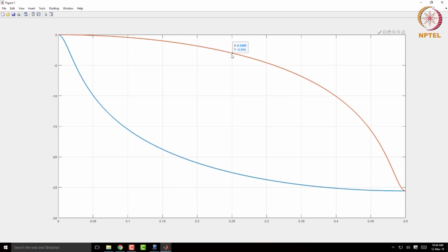So in general, poles provide sharp peaks, and hence you can expect the frequency response to be realized with a much lower order filter if you had both poles and zeros to play with, as opposed to playing with only just zeros.